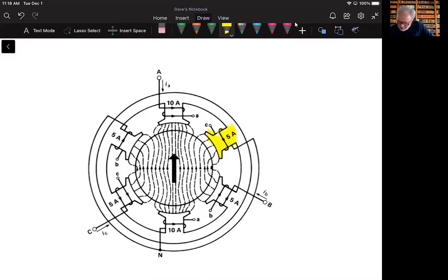They actually look like that in the interior of the motor, and early AC motors were built this way. You created these electromagnets by taking a coil of wire and wrapping it around that protrusion, that salient pole, and running current through there causes the magnetic flux to occur.